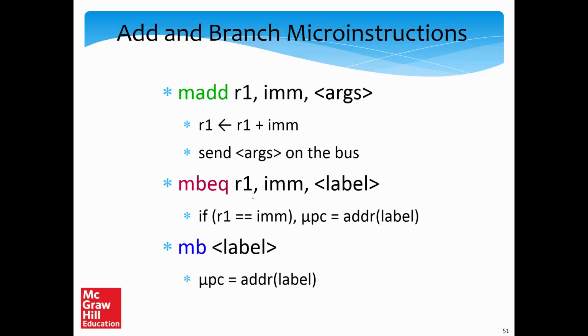We have a few more. So we introduced three very basic micro instructions, which are required for every instruction, namely mload IR, mdecode, and mswitch. We then introduced two generic move instructions, mmove and mmove I. One to move a register, one to move an immediate.